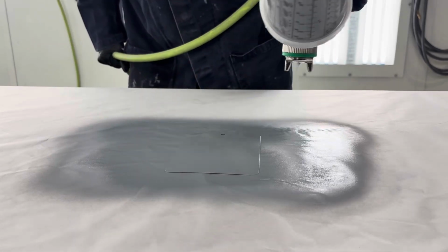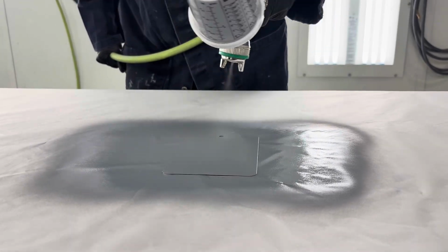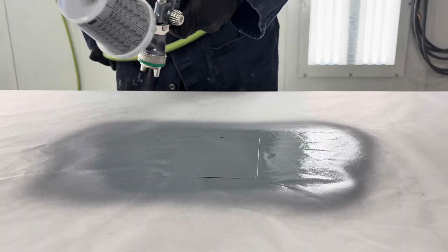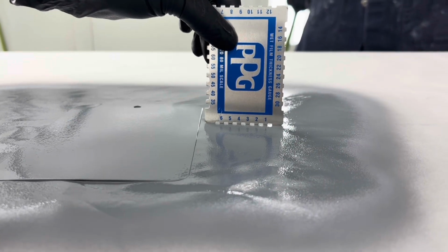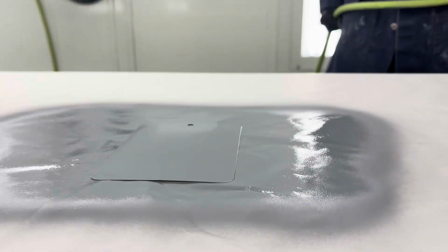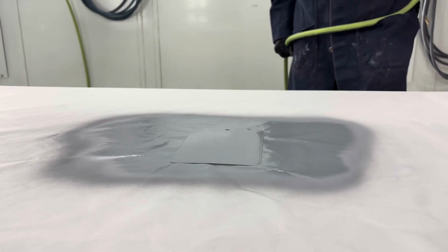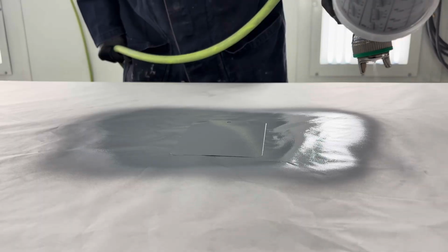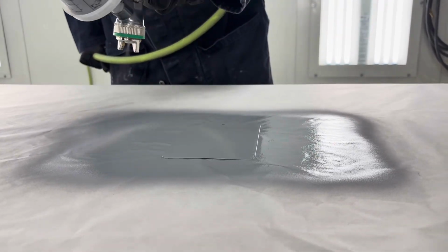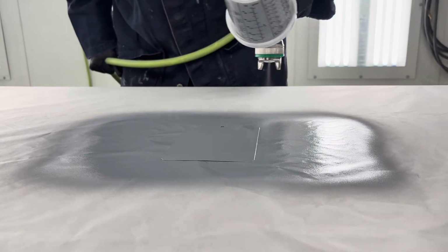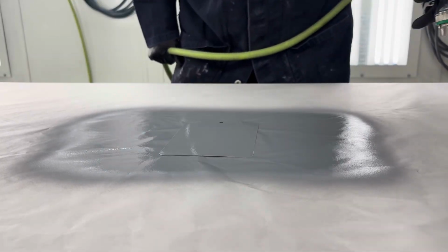Essentially what happens is each of the little edges on the side of the gauge are longer than the others by 1 or 2 mils. As we insert this, we'll see marks or we won't see marks. If there's a mark in there, then that means that the coating has reached that level. So we look at the next one and we look until we don't see any marks anymore, and then look at the number that corresponds to, which tells us the thickness of the material.